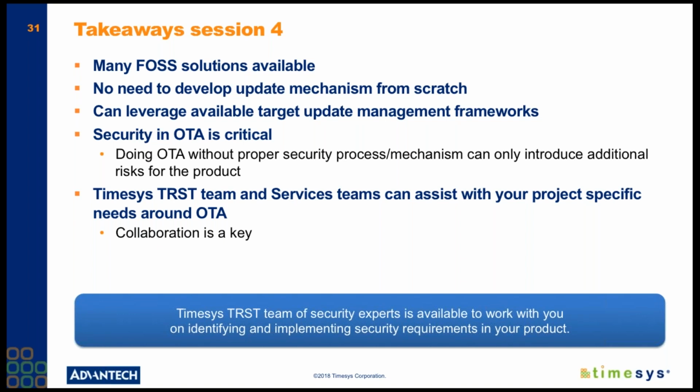The hardware support for one-time programmable keys typically can support more than one key, but the use of trusted platform modules, TPMs, extends that even further. So this would allow you to deploy multiple public keys in a secure way. And those public keys could then be used to validate different software update images. But of course, that would have to be engineered and designed appropriately.